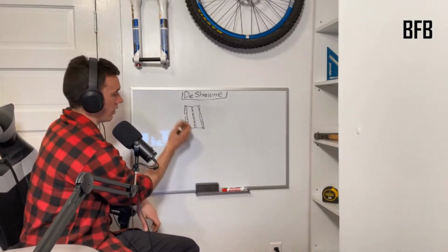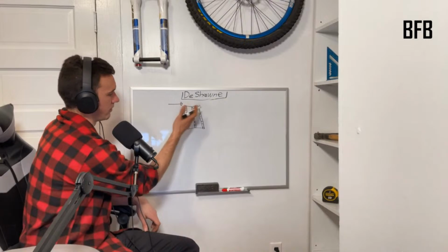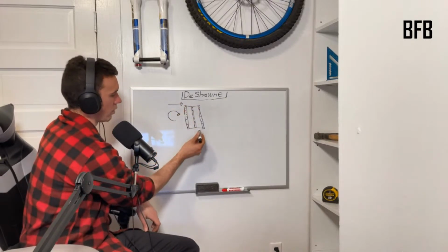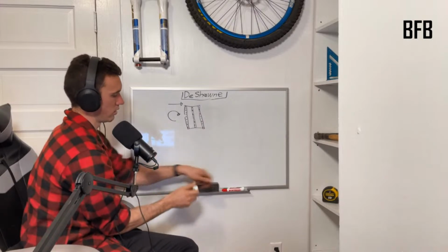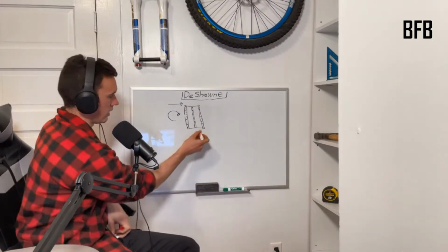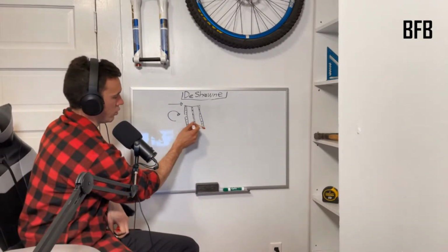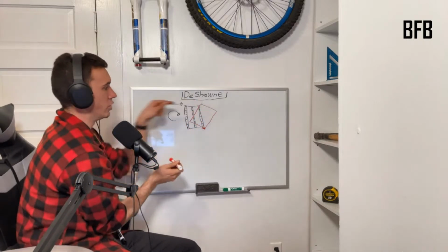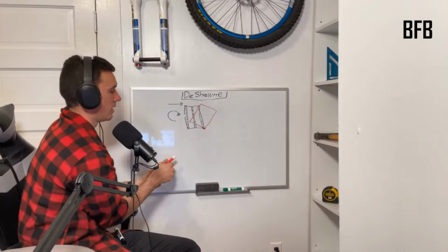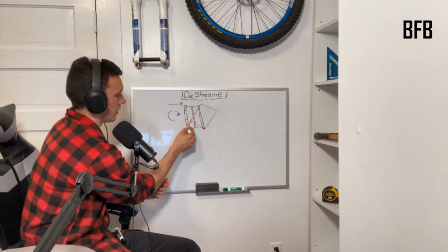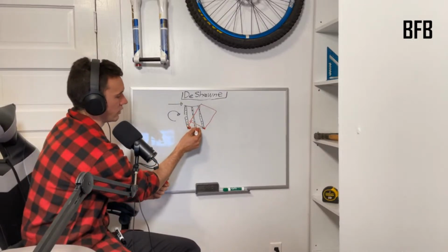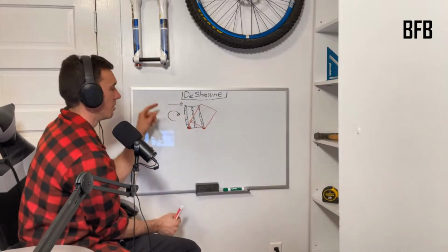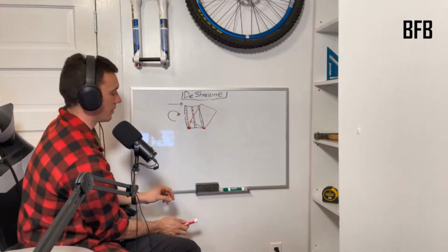So if the diaphragm is loaded from the side, let's say it's like a sheathing panel on a shear wall, top plates are pushed sideways. This whole thing's going to want to rotate about this point, basically, and tip over. That's what the wind is trying to make it do when it's pushing on the top. But it doesn't do that because this is anchored down to the ground and bolted. It's actually nailed also to the bottom plate, which is anchored to the foundation and all kinds of good stuff. So they don't go anywhere. But that's what it's trying to resist.